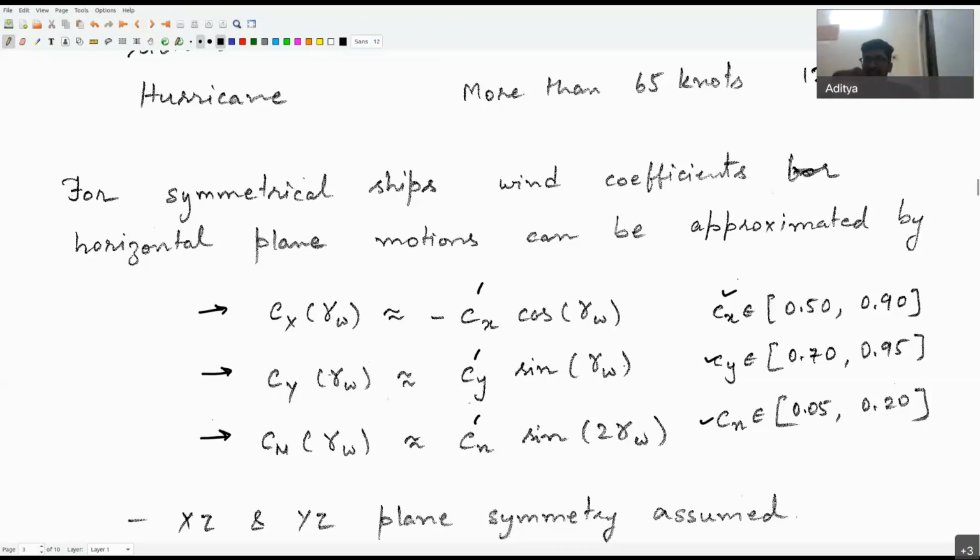right? When the wind is actually going sideways, you won't expect to see the vessel yaw much, is what I'm saying. It may not really be exactly 0, but it will be close to 0 in a real typical scenario, because your superstructure might be contributing a little bit of a moment. But more or less, the windage area should be matching, so the value of the yaw coefficient must be coming down as I come towards a perfectly beam condition.